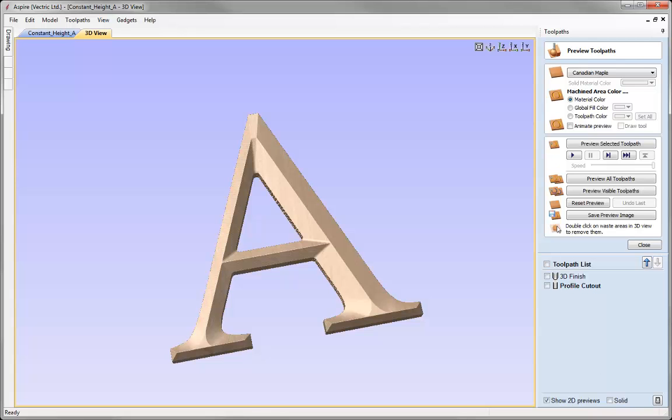There's a few different conclusions that we may come to having watched this example. One is that this is quite a complex process, and so we'd prefer to work within the confines of what the Prism toolpath will give us. However, if you do decide to do it, at least you've seen how the technique works, how we can use the vector construction and the power of the two-rail sweep to really give us a great deal of control over the shape that we want to make. And that concludes this video.